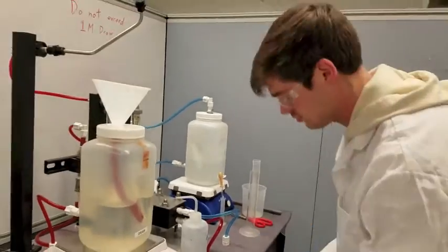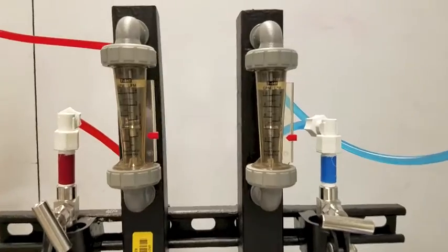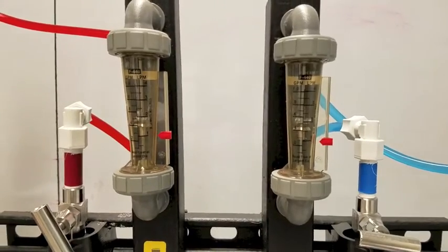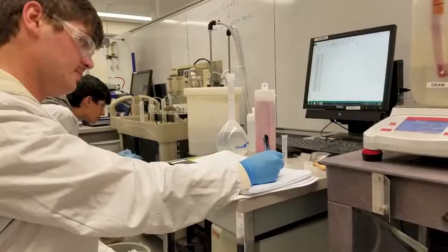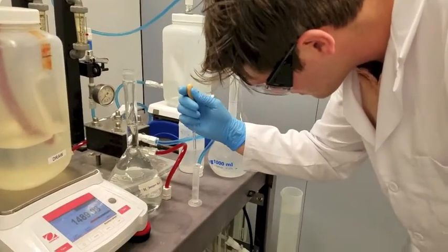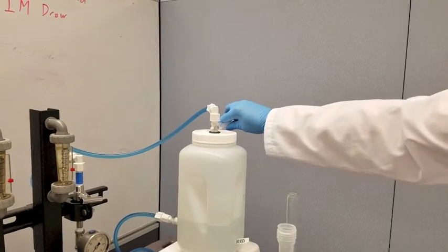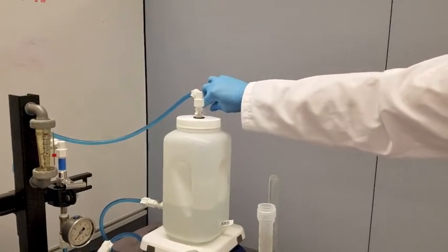The pumps must then be turned on and given enough time for the flow rates to level out. Both pumps must be operating at the same flow rate for the experiment. Now you're ready to begin taking data points with the software. Once the weight of the draw solution maintains a constant weight, you can begin to add the salt solution in order to begin concentrating the mixture.